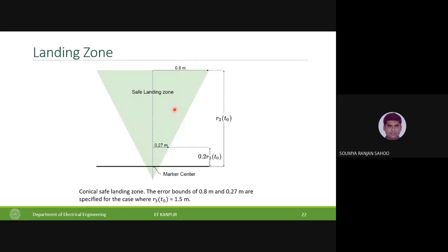Now what we found out was that with the simple PID structure, it was not able to land because with the slightest disturbance it would come out. So we made a slight change in the controller. We used an adaptive position controller based on the image that we were getting. We tried to estimate the acceleration and velocity from the ArUco marker and use that in our feedback. It helped us maintain the quad in the safe landing zone. I think I do not have the failure cases plotted here, though the failure cases were available. I think I forgot, but let's see the successful ones.